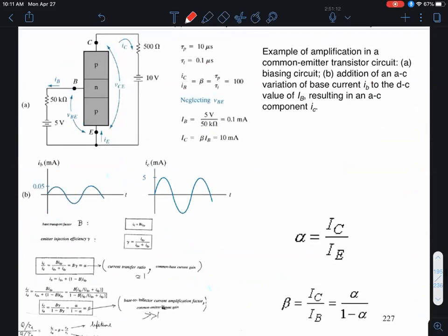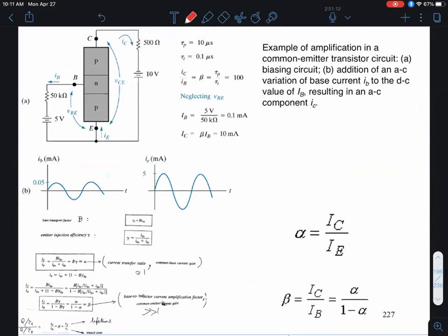On the other hand, if you operate a BJT in the so-called common emitter mode, as shown in this figure over here, that's called the common emitter configuration, you can get both voltage and current gain, and of course also power gain. An active device, by the way, remember, is one which has power gain. The change of power at the output is more than the change of power at the input. So input power has to be less than the output power. That's a hallmark of an active device like a transistor: power gain.